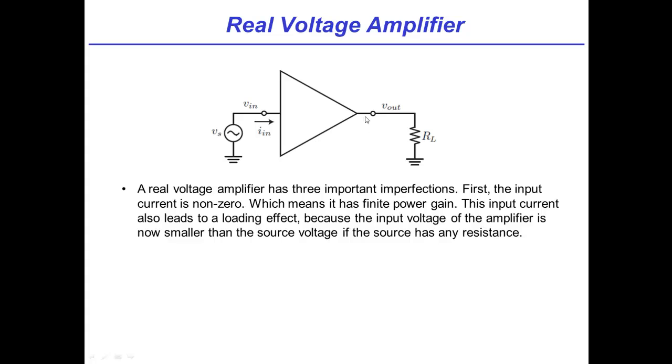So the output power here would then be V_out squared divided by R_L, based on the physics we learned earlier. So I have a finite input power, I have a finite output power, and therefore I have a finite and knowable power gain. Right. It's a finite ratio. If I_in was 0, then you would have some number divided by 0, and you'd get infinite power gain.